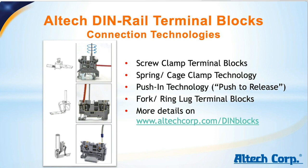However, when we make that connection, we need to watch out that we have a safe connection. We don't want to over torque the terminal. This could strip the screw or break the terminal completely, so we would have a loose wire. On the other end, we also need to make sure we have enough torque. If we don't have enough torque, we could also have a loose wire in the terminal.